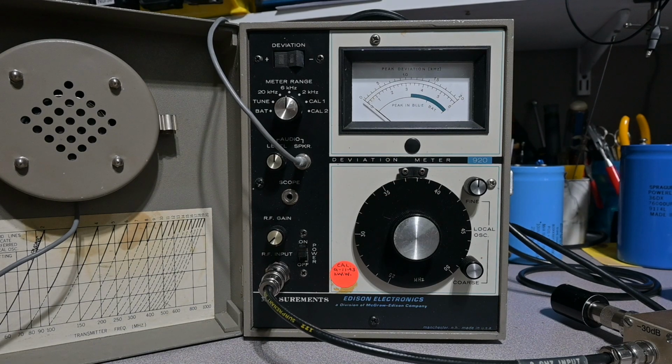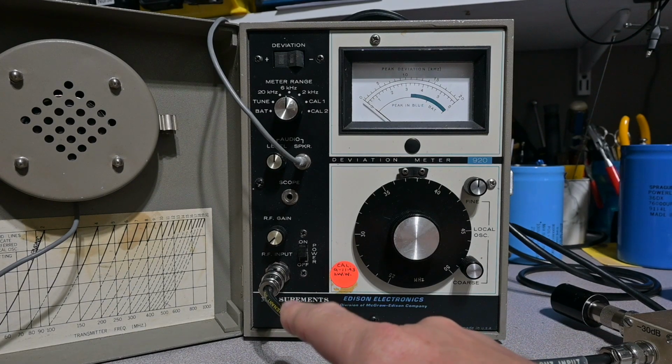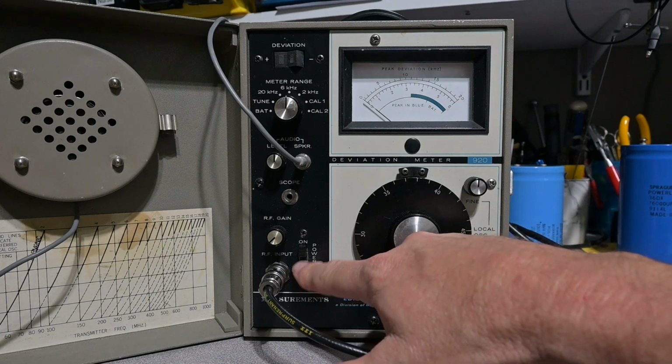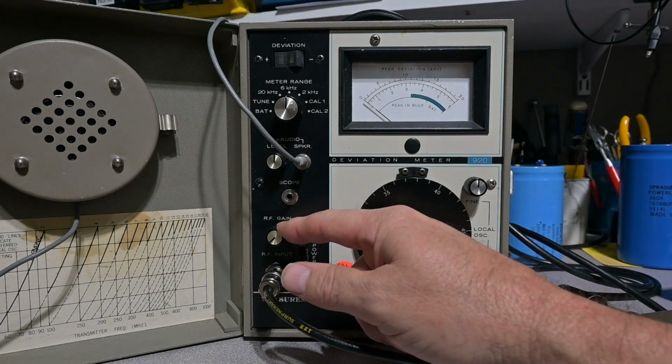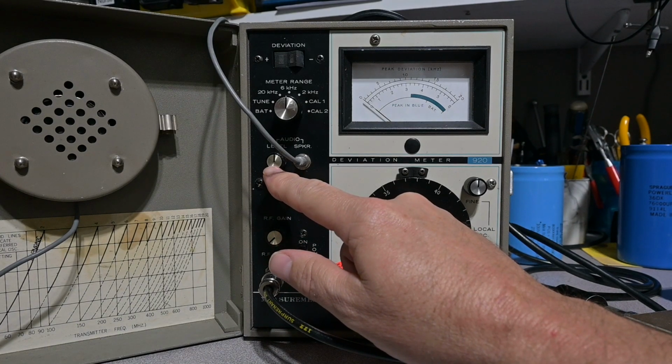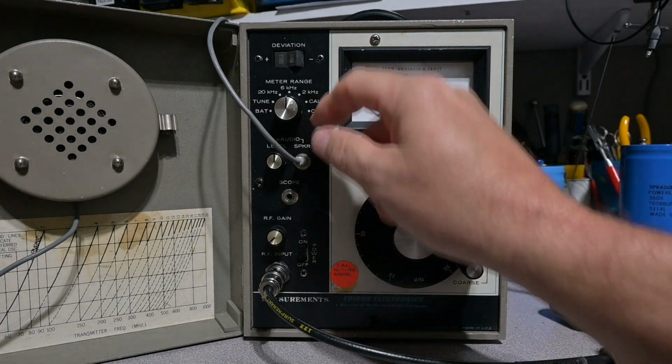Now that we understand the instrument, its controls, and the configuration of the device under test, we can go ahead and perform our test. We're going to check a portable radio on a 25 kilohertz channel, 146 megahertz in frequency. We go ahead and connect our device under test to the instrument, turn our power on. We turn our RF gain fully counterclockwise. We take our audio level, center it, plug in our speaker.